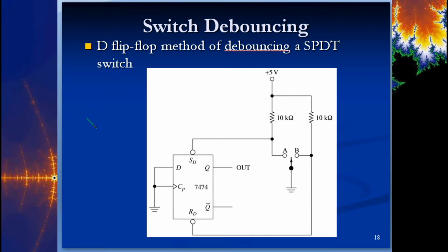This is yet another way to do it, with a D flip-flop, and just have each one of these selectors tied up to a set and a reset, and then here is your voltage out as well, for a Q out. And so you have essentially the same setup here. So what you're going to do is either send a low to this side, and this side will be high, or send a high to this side, and this side will be low. So only one of the two is going to be active at any point in time. All right, so walk yourself through this.